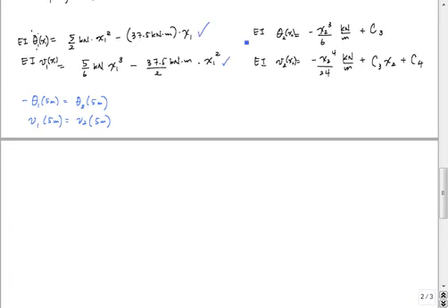Now we want to apply the other two boundary conditions where the two functions meet, where x1 and x2 meet. I just rewrote the boundary conditions here, and I'm going to apply these one at a time. I'll start with theta 1 equals theta 2. I just want to plug and chug straight up. So EI theta 1 at x1, or at 5 meters, is equal to the negative of EI theta 2 at 5 meters, right here.